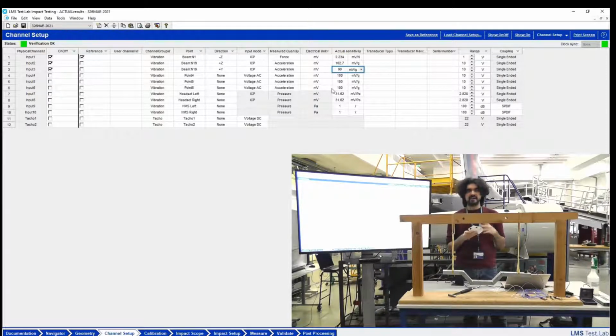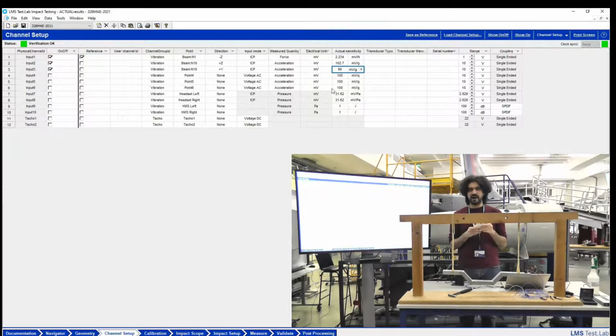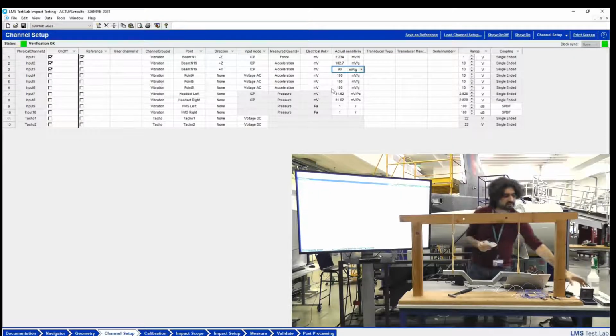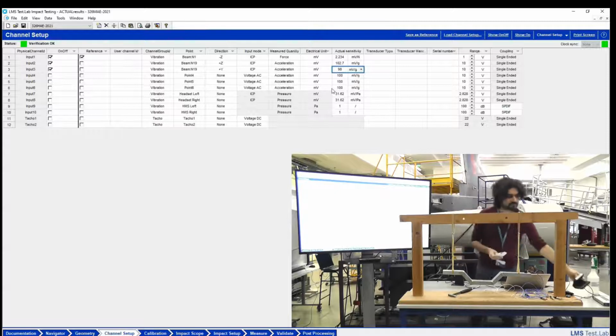These sensors need calibration, every 3 years, every 5 years, or every year, depending on how critical your industry is. They need periodic recalibration. After a set of 3 years or 5 years, you might want to return these instruments to the company that recalibrates them, and then it ships them back to you for a hefty fee.